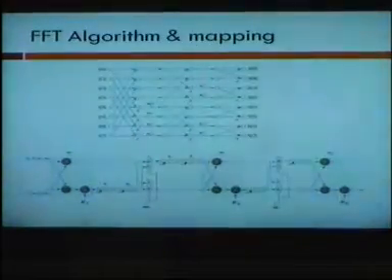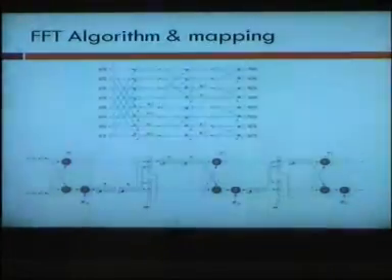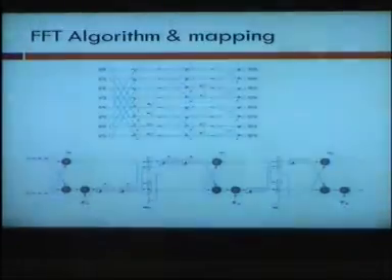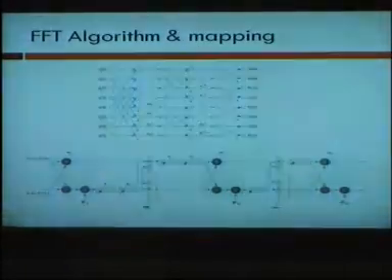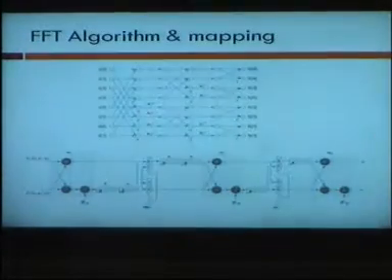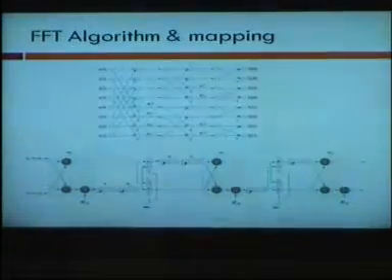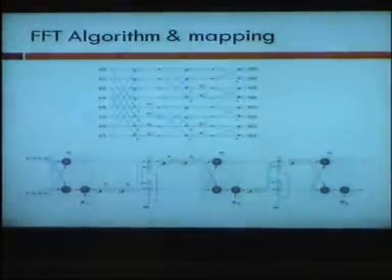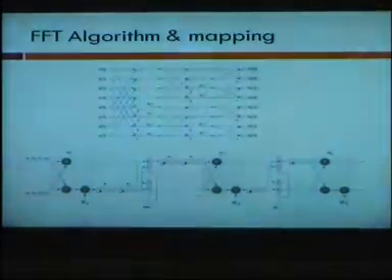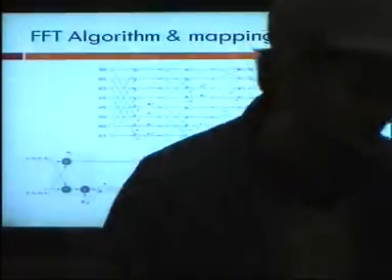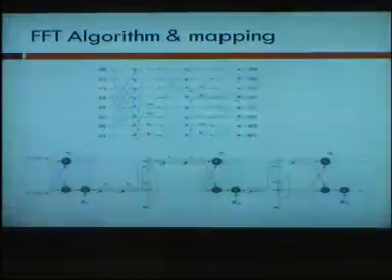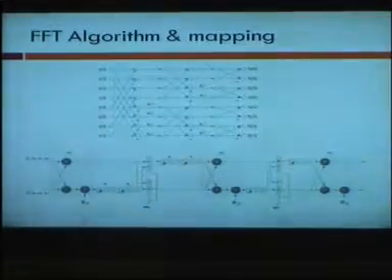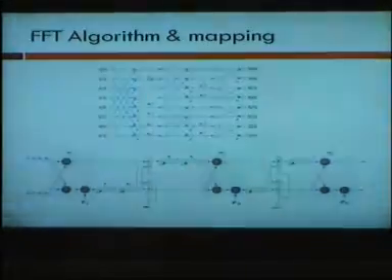So sometimes you say it is not the algorithm or an implementation in C that will better help you to implement that algorithm in hardware. Rather, it is the flow graph, because a flow graph gives you better visualization of the activities in that algorithm. So sometimes you say, let's draw a flow graph. A flow graph will give you an easy mapping. But a flow graph, again, is not an architecture. A flow graph is an expression of an algorithm. So this is a flow graph of the fast Fourier transform.